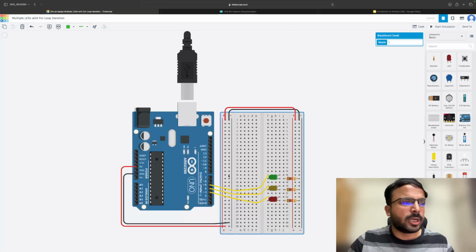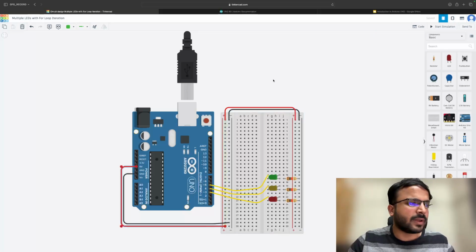Again, we start with the breadboard connection, enabling the breadboard to drive multiple voltage levels and connect many peripherals. Suppose you have 10 LEDs. It would be very difficult and messy to connect all those LEDs directly to the digital output ports here in the Arduino. So the breadboard gives you that clarity and much clearer ports to connect. What we did, if you see, we gave this red plus 5 volt. Now we took this black row as 0 volt, ground, and we connected the top minus and plus to the same 0 and 5 volts.